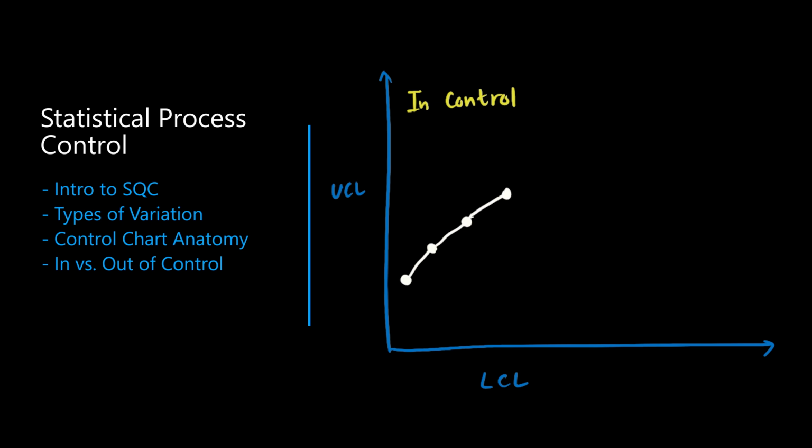However, if a data point falls outside the control limits, or if you see a non-random pattern of points inside the limits, like 7 points in a row all going up, this is a signal that the process is out of control. It's a red flag telling you that an assignable cause has likely entered the process, and you need to stop, investigate, and fix the root cause.